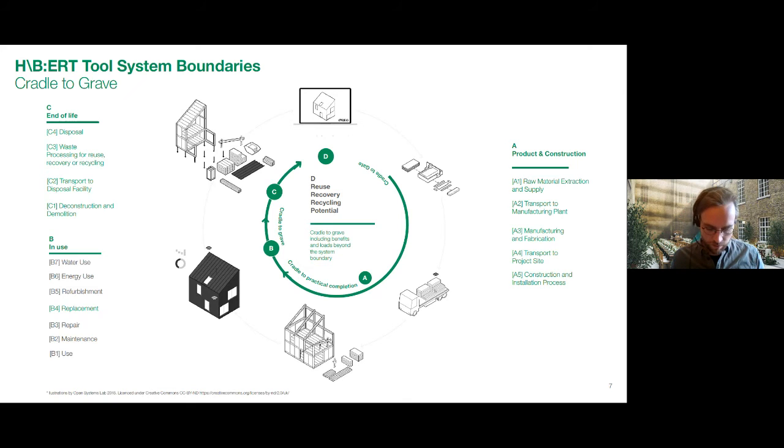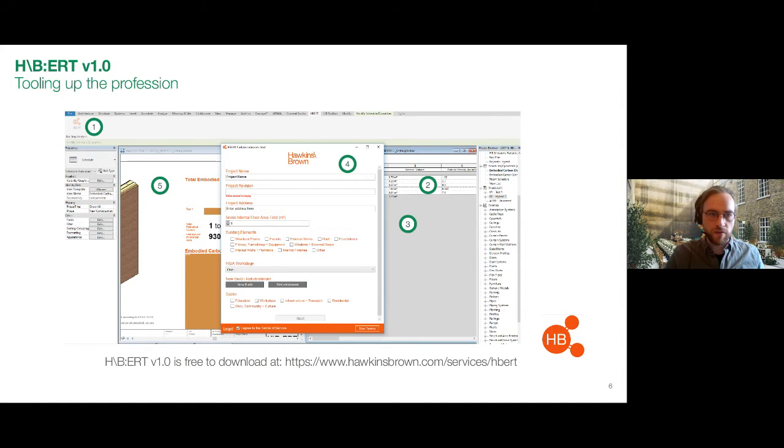What I think is fantastic about this tool is the way that it works. I'll get to that in a minute, but here is how it looks in your actual Revit screen. Number 2 in the background is a little clip of how we record the data, which is in custom schedules. If you know about using schedules in Revit, you can export all that schedule data in several different formats, including ones you can just open up in Excel. That gives you access to basically all the raw data and lets you modify it in any way you want.